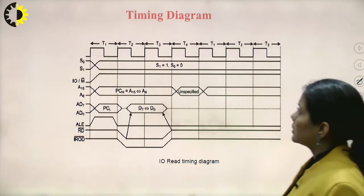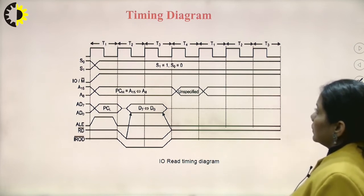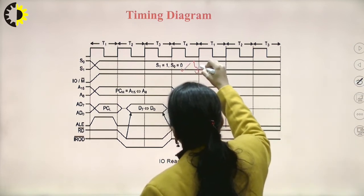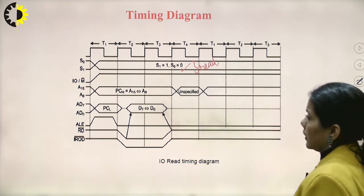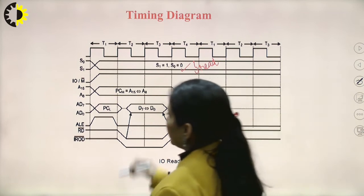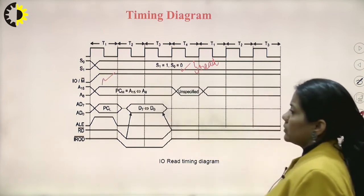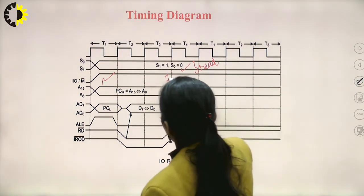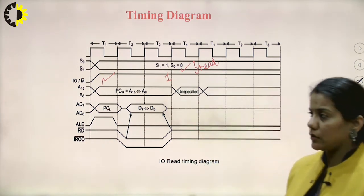Let's understand this using this diagram. Here S1 is 1 and S0 is 0. This is the condition for reading. Again, IO/M-bar: this is the input-output operation. That's why this signal is 1, that is, the state is high. If it had been a memory operation, then it would have gone low.